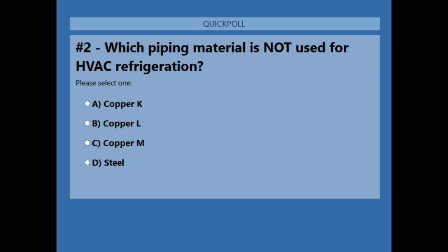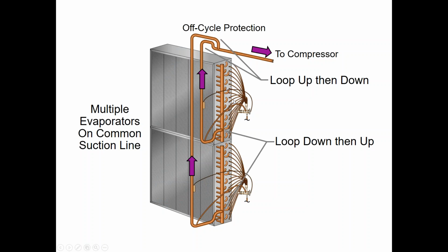I'm going to say that probably 90% of the coils that we select or build for you are intertwined coils now. So the only thing you need to make sure of is you're not doing face split. We want both coils active all the time, through your intertwined or row split setup. All right, okay. That makes sense.